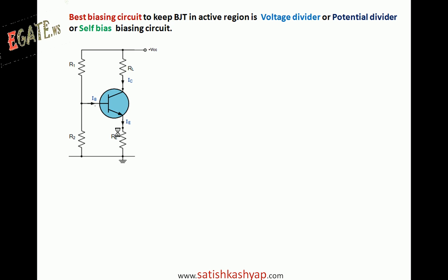And since you are applying constant voltage and resistor values which you are not changing, that is they are also constant, what we expect is constant currents flowing in the transistor. Those constant currents are called DC currents or quiescent currents, and because of that there will be a constant voltage across the transistor terminals. They are called DC voltages or quiescent voltages.